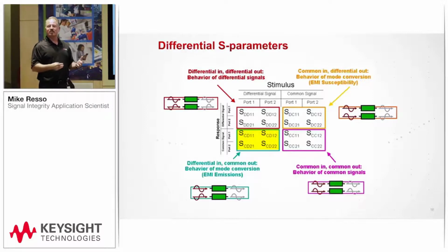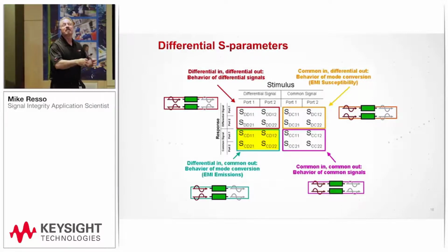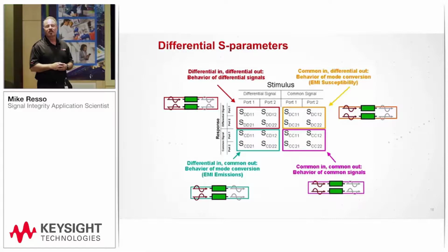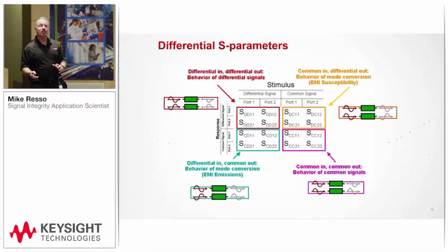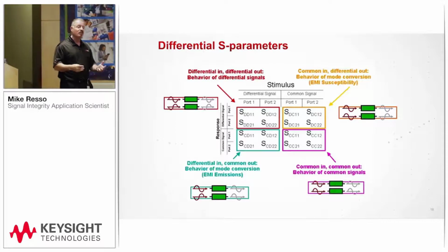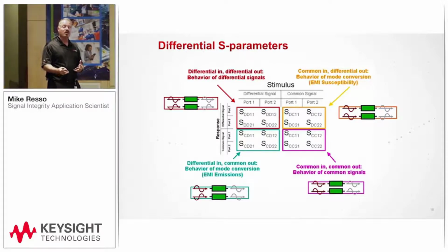So now you could have a source of crosstalk that will contaminate the rest of your board. So there's a nice correlation between S parameter mode conversion and crosstalk that can give you a lot of hints as to not only the magnitude of crosstalk, but we can also find out where in the channel spatially it's happening.